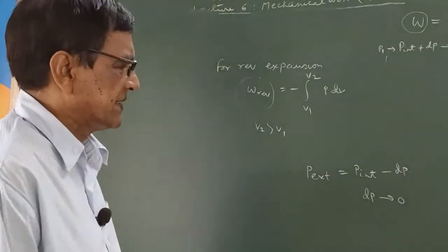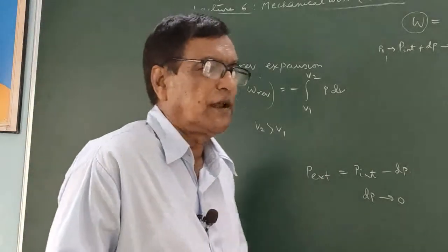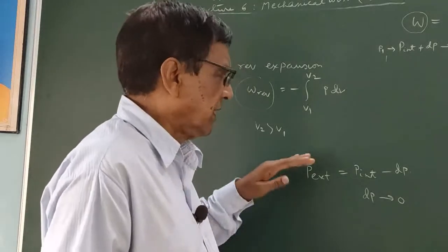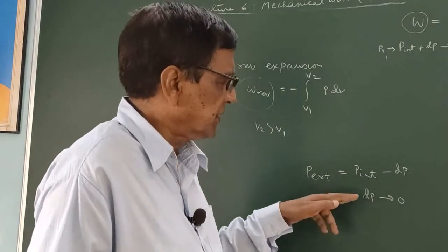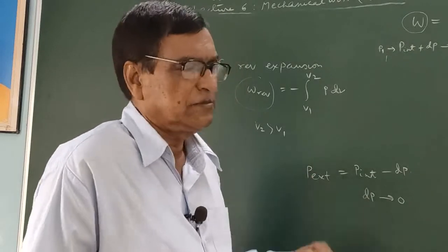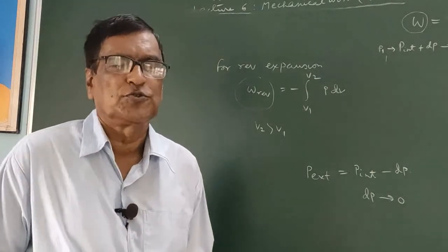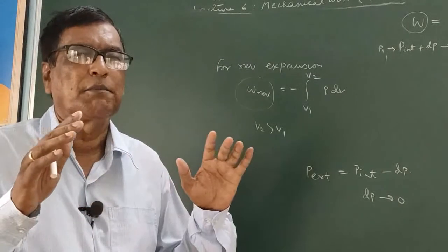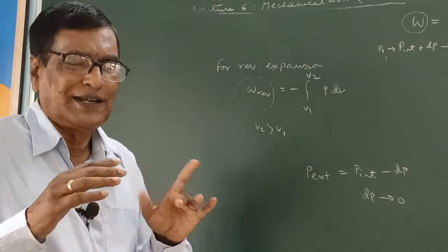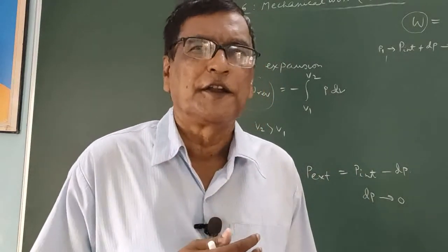So in this case, this external pressure is always kept maximum for the expansion of this gas. So in every step, the external pressure is kept maximum. So overall, this reversible process will also give the maximum work done by the gas. This is why, if we would like to get the maximum work, we always prefer the reversible process.